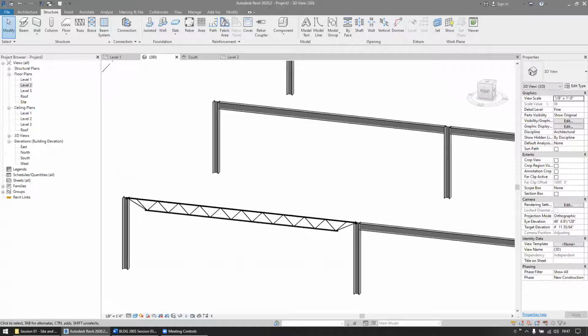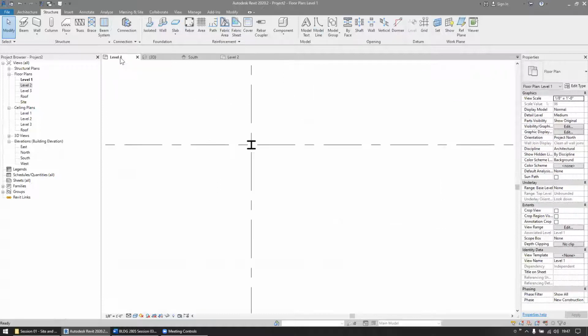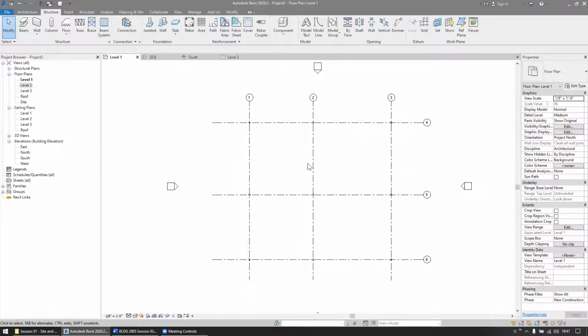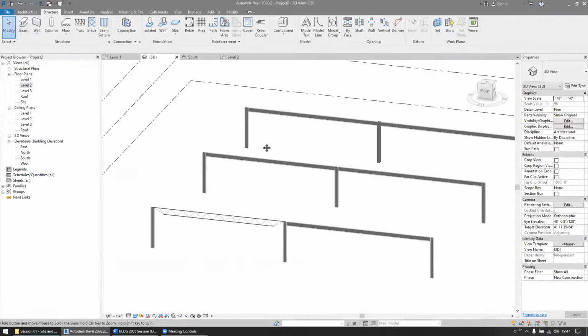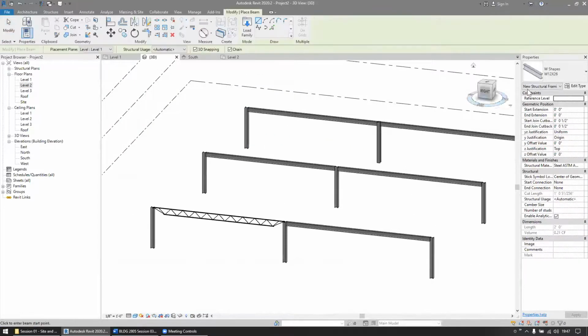So these beams can just be placed in 3D. And so in the notes, it says at the bottom of page 2 here, if you want to see those beams after you've placed them in a floor plan. So let's say I want to see those beam locations that I've placed in 3D. So here, I can 3D snap from one beam over to the other. So you can see I did a snap perpendicular there.